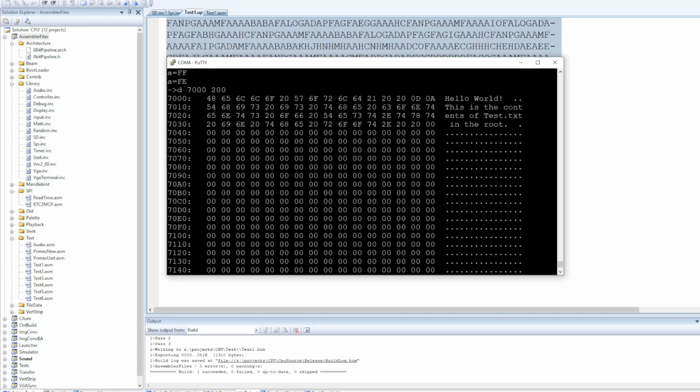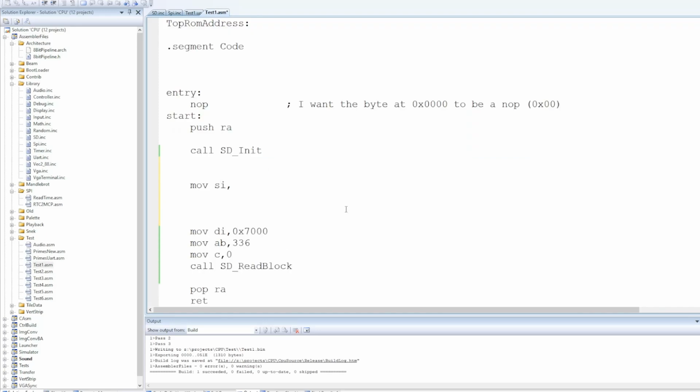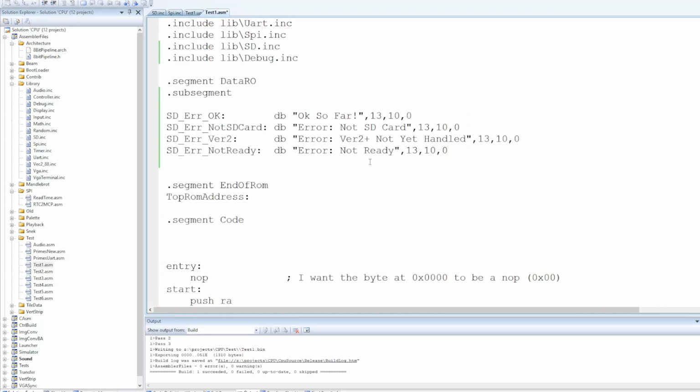I definitely need to do more work, particularly on the initialize, give it some better error handling, probably on the read as well. I need to support high capacity SD mode on the read. So the initialize will need to store some state off. But the initialize and read as an external interface is 2/3 of what we need. We want a write as well. Need to move those into my SD library as well.